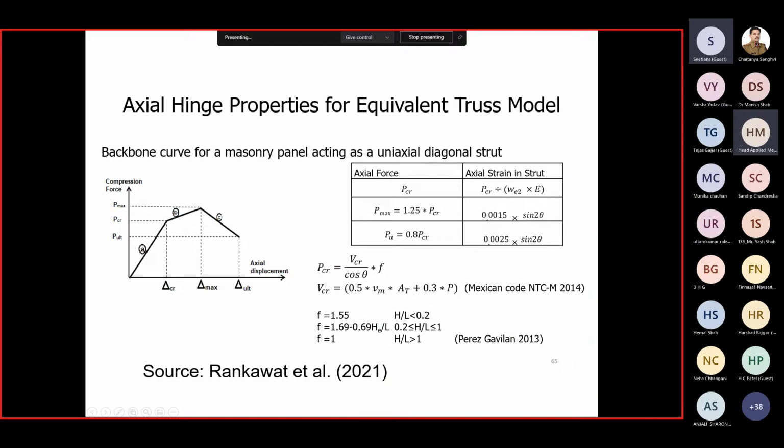For the plastic hinges, she assumed that there is one for shear, which is critical for this case. She assumed similar behavior like what Professor Juan Jose explained before, and that was force deformation behavior for the strut: a first initially linear stage, then start of cracking, then maximum ultimate capacity, and then the failure. So this was all simulated in a model, and this is the so-called backbone curve or force displacement curve, which is an input for the nonlinear model.